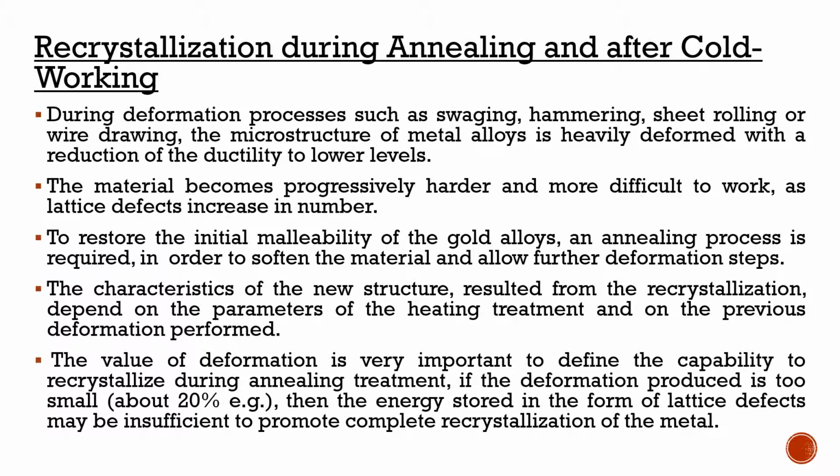The characteristics of the new structure resulting from the recrystallization depend on the parameters of the heating treatment and on the previous deformation performed. The value of deformation is very important to define the capability to recrystallize during annealing treatment. If the deformation produced is too small, then the energy stored in the form of lattice defects may be insufficient to promote complete recrystallization of the metal.